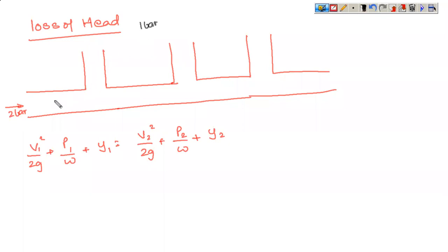When fluid passes through this location, it will rise to a certain height H1, corresponding to a pressure P1 given by rho g H1. This height corresponds to approximately 1 bar. So you have 2 bar entering here, 1 bar is the pressure head being generated, and 1 bar is the atmospheric pressure, and it balances itself.